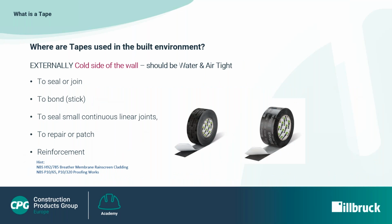Expanding impregnated foam tapes like Illbruck Compriband and other familiar variants will be dealt with in another topic in this series. For now, we'll focus on tapes used in proofing works. Tapes used externally on the cold side of the wall should be particularly robust. Tapes must be able to demonstrate resistance to liquid water penetration, have resistance to UV degradation in cases of prolonged exposure, and be airtight when required.